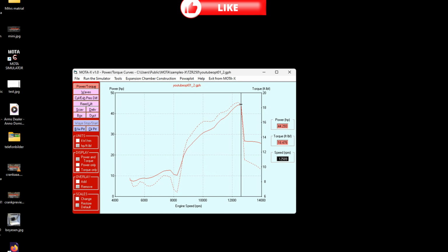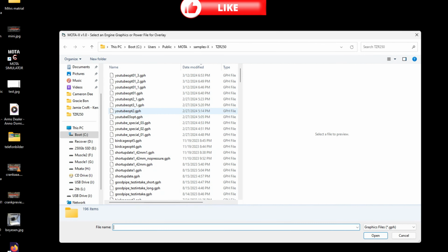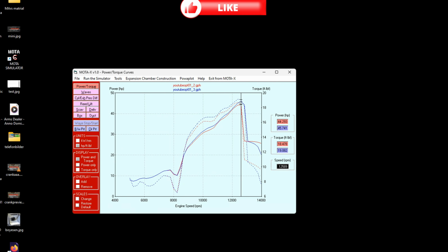And now I'll add the new fuel curve, see if there were some changes. And now you can see it starts to round off. So it was fuel that was not correct. Well, it doesn't start to round off, it's peaky, but you can see the shape is more like a usable design. And I got some more over rev, so to speak.